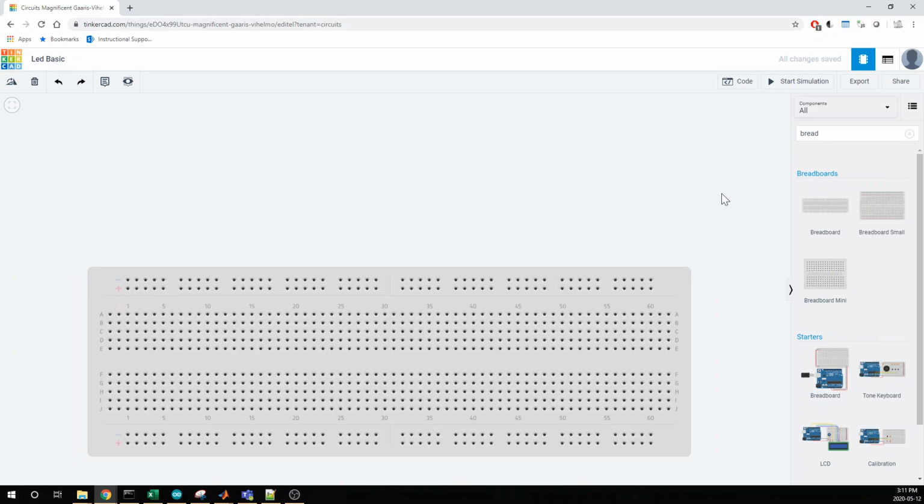Now, the next thing, when you're building any circuit, is to build the circuit components unpowered first and then power it. In Tinkercad, it really doesn't matter. If you blow up a simulated LED, whatever, you just reset and try again. But when you're building real circuits, if you try to connect power first and something goes wrong, you might end up shorting your actual power supply itself, and blowing up a power supply or whatever it happens to be. So it's always a good idea to start with components first and then power them. And that's why the rails are so important, which are here.